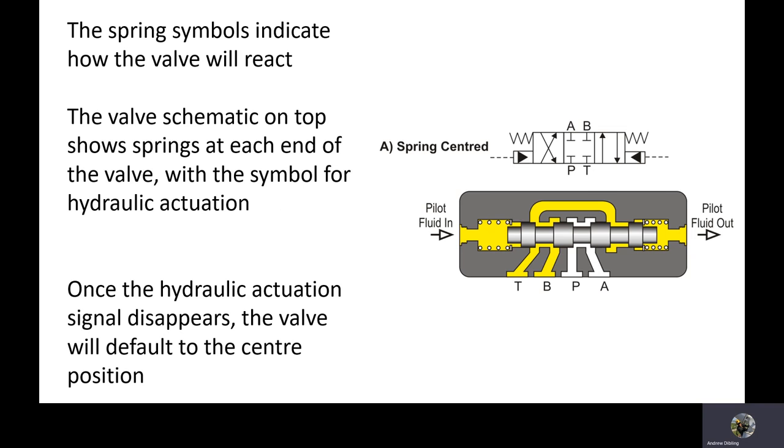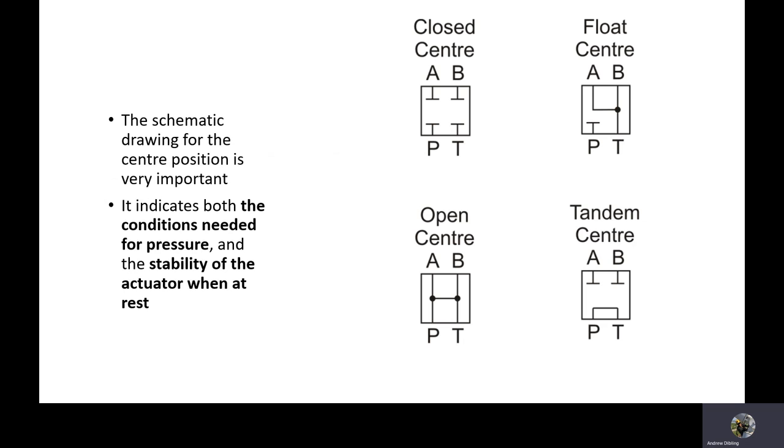So here you see that the channels that are actually cut into the valve body are what actually determine where the fluid goes. All the spool does is move in and out, back and forth on both of those springs, depending on which way the pilot fluid determines that the spool should be pushed. Very simple design, but very robust. And you get a lot of actuations in one of these devices in a long lifespan.